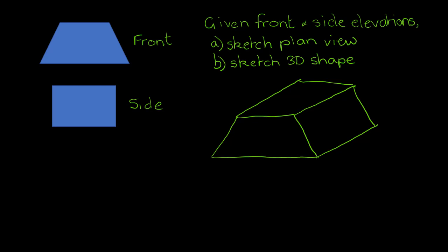So to draw the plan view, first of all, draw the top, if you like, of the section. It would look like this. But then you would also be able to see something of the sides. They won't be as wide as they look there. So your full measurement should be the same total width as this and not any bigger.